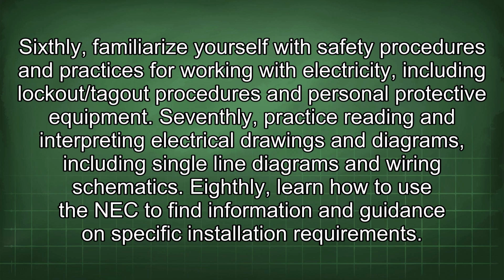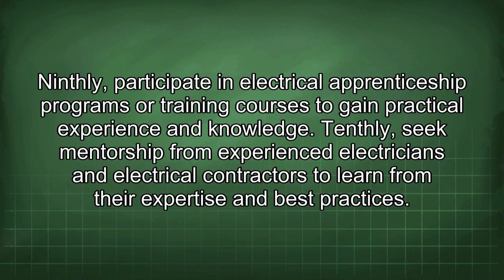Seventhly, practice reading and interpreting electrical drawings and diagrams, including single-line diagrams and wiring schematics. Eighthly, learn how to use the NEC to find information and guidance on specific installation requirements. Ninthly, participate in electrical apprenticeship programs or training courses to gain practical experience and knowledge. Tenthly, seek mentorship from experienced electricians and electrical contractors to learn from their expertise and best practices.